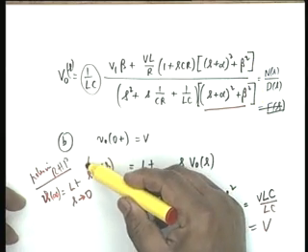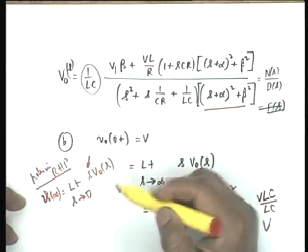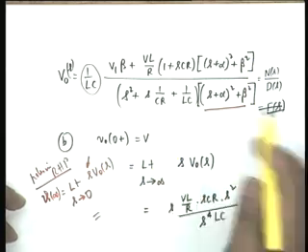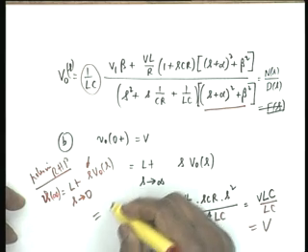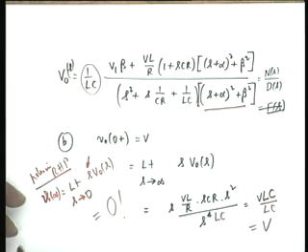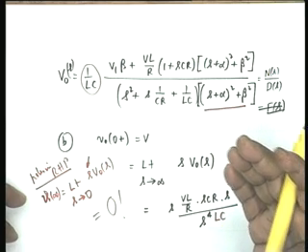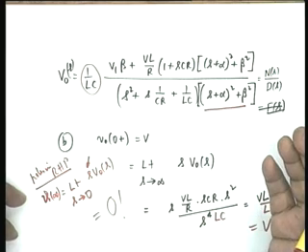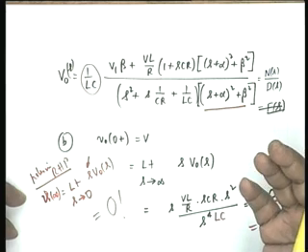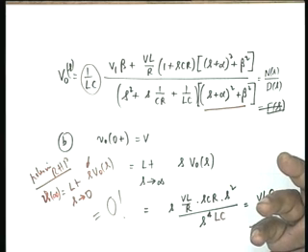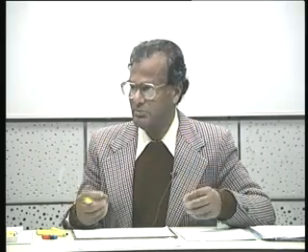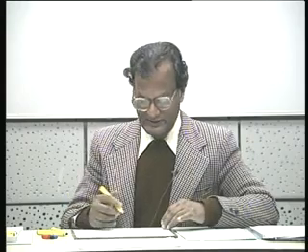There is a multiplication by S, and when S tends to 0, whatever the other quantity is, unless it is infinite, it is a big 0. And this also tallies with the physical concepts. The source itself is an exponentially decaying source, e to the minus alpha t sine of beta t, and therefore, after an infinite amount of time the capacitor will discharge completely. There will be no source for charging, and therefore, the voltage shall be 0.